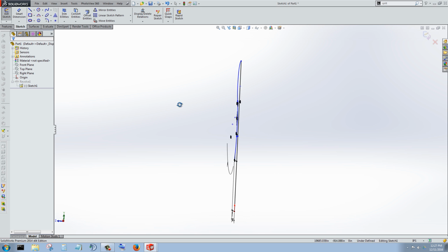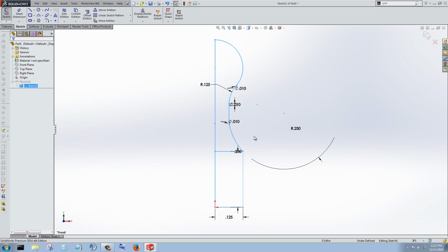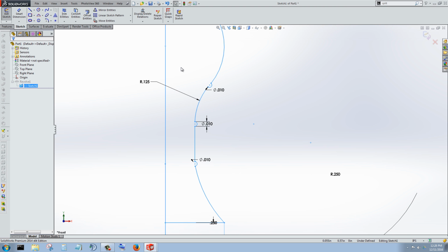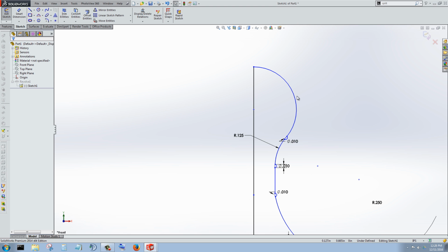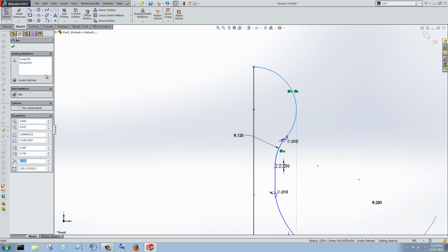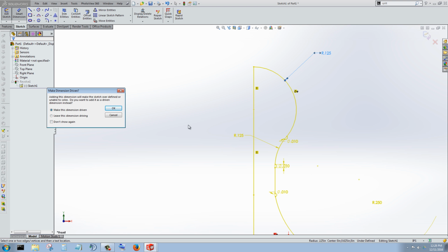And I could try and do this and that, but something nice here in SolidWorks, I right click and I see this button, I go normal to. I want to make my view plane normal to the sketch plane. Perfect. So now I'm right at a perpendicular view. Now this, I don't think we dimensioned this. We just said, hey, make it tangent.